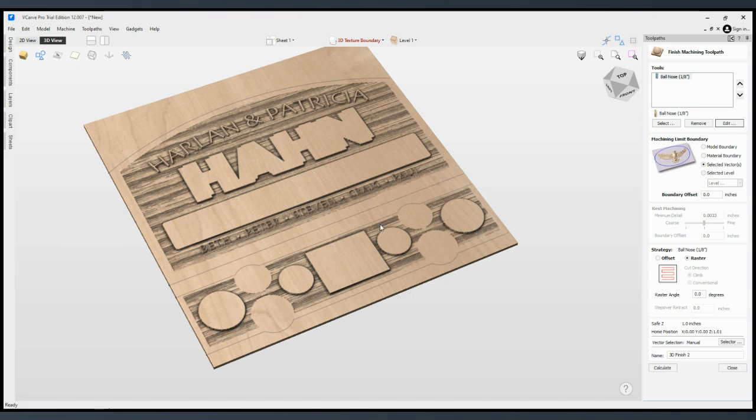If we make it bigger, it will decrease your cycle time. You'll get a less quality finish, but it cuts it faster, right? So those are some settings that you look at to adjust how fast you're cutting along. These are some settings here to adjust. That's for the 3D, okay?